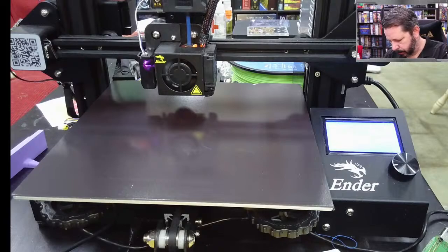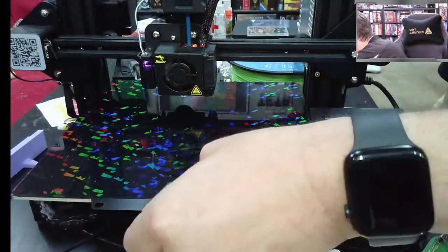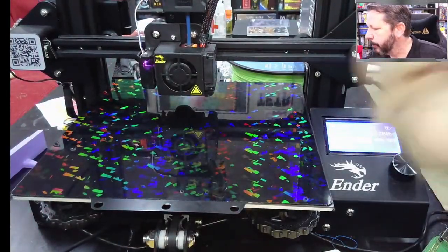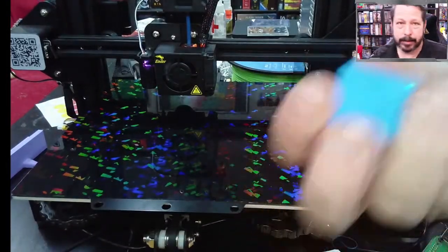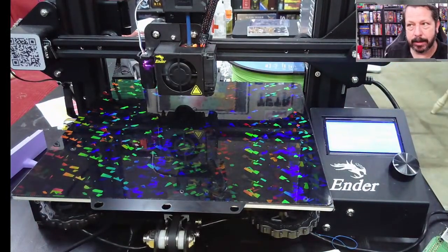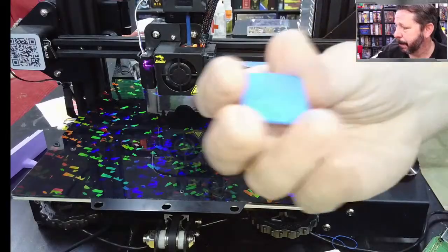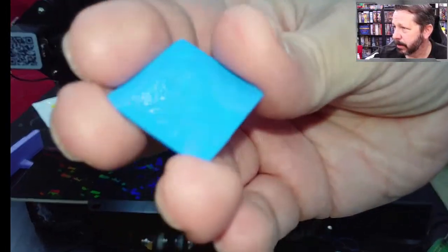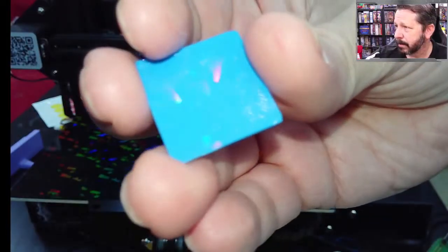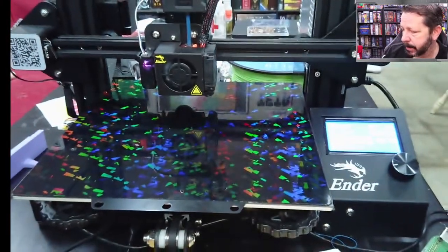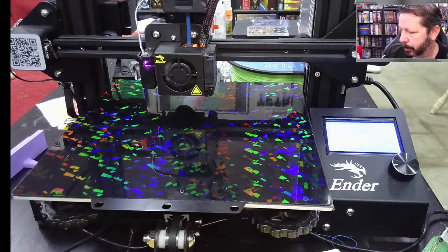So there's different ones, and they all will give you some different patterns on whatever you print on the bottom side. So you have to orient your part so that maybe it's a control panel or whatever, the part that you're actually going to see ends up facing the bed, and then it'll put that pattern onto your surface. Kind of like the textured PEI, except these add a little bit more interest.